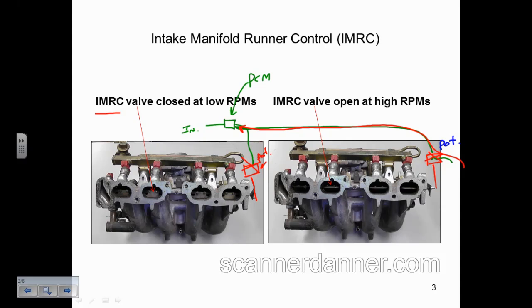The test that I used to do when I checked them, I would take my section 3 information I've given you guys: check the solenoid, power or ground side switching, energize the solenoid manually, and then look for the actuators to move. When they wouldn't move, the next step I would take is to take the vacuum hose off of this one, plug my finger over the line and redo it while I'm watching this side. And if I saw this side now move, then I know for a fact that this diaphragm in here is torn and that was causing the problem.